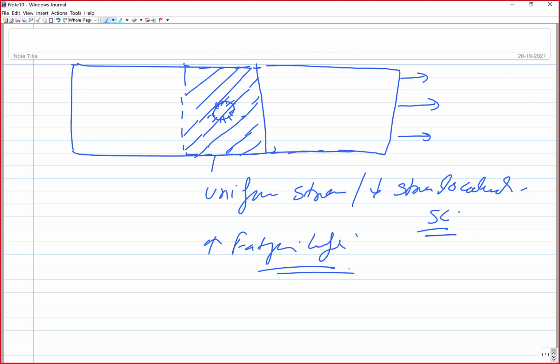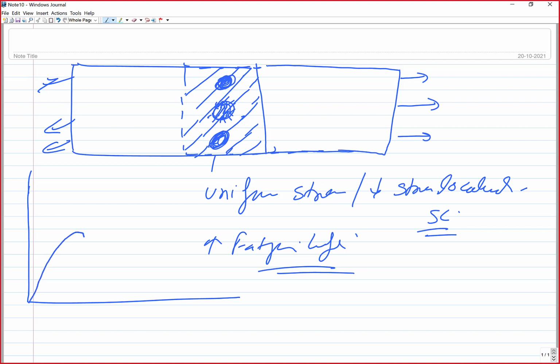Let's take an example. This is a weld bond having spot welds, made like this, 1, 2, 3 in the same line, and an adhesive joint, subjected to fatigue loading. Now, when a tensile test is performed, how does it behave? Initially it will go like this, then again it will go like this. This dip or deviation is an indicator of the adhesive failure.